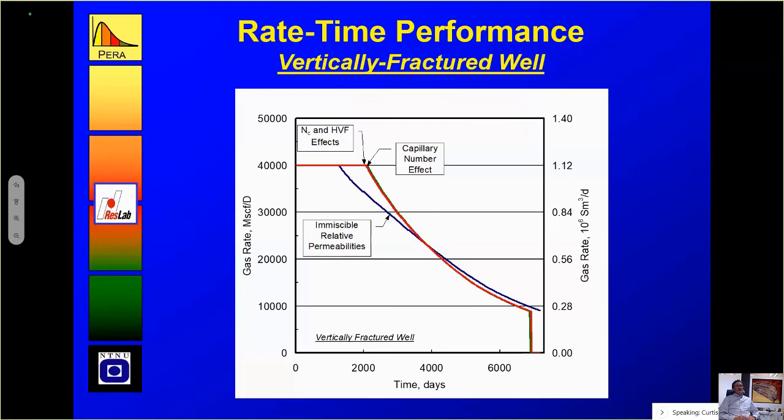Okay, but let's say that you have a 5 millidarcy rock. In the first foot, it's 1 millidarcy because of this leak-off damage, okay? Yeah. And then in the hydraulic fracture itself, there's restriction there too. So the fact that you have the damage of 1 millidarcy in the first foot just by damage, if you put on top of that the condensate blockage, then of course it's worse than just having damage. But I'm not sure